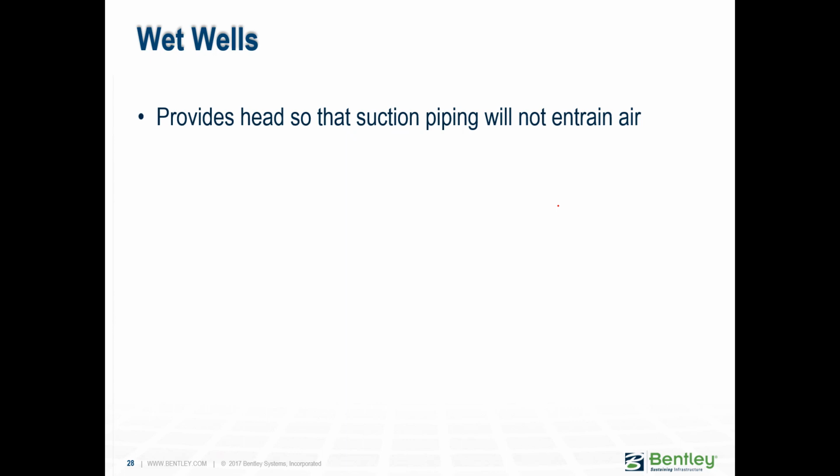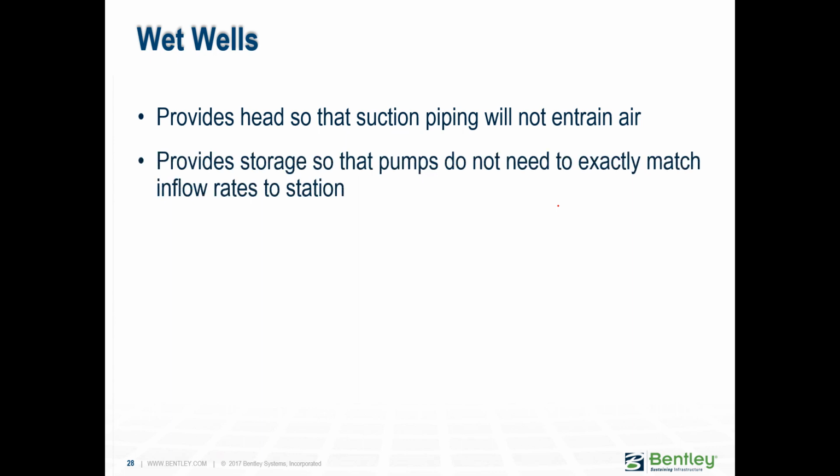So what about a wet well? What is a wet well? Well, a wet well serves a number of functions in a system. First is providing that head at the suction of the pump. Remember, we said we need to have a good head at the suction end of a pump, so there is no cavitation. So that's purpose number one.